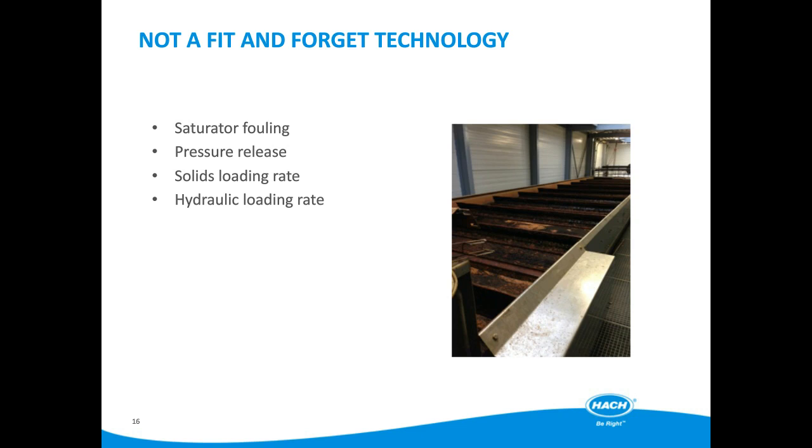Eductors are also not maintenance-free. The nozzle or pressure release valve where the pressure of the recycled water is released, causing the production of microbubbles, is particularly prone to erosion due to the high velocities and different densities of water and air. This erosion will inevitably wear away the surfaces of the pressure relief valve, reducing efficiency and affecting the bubble size.